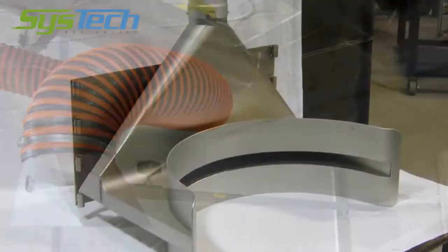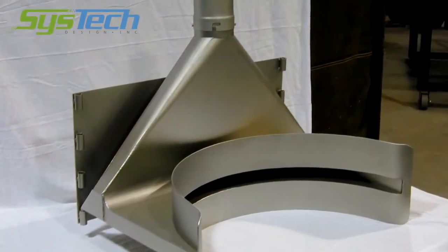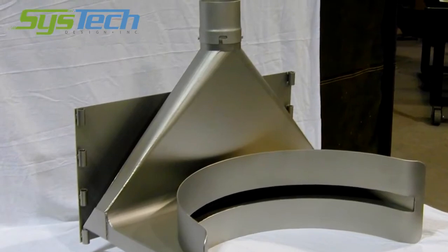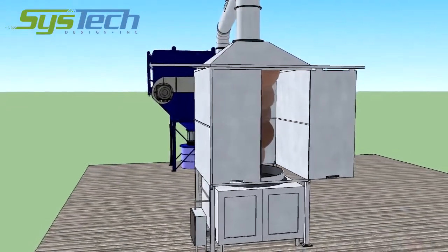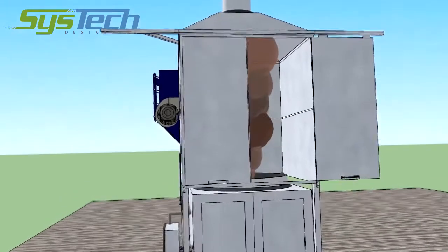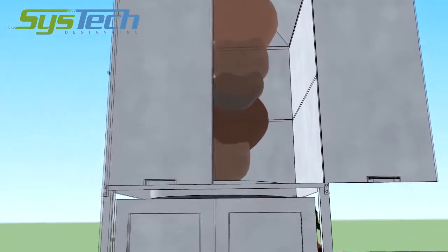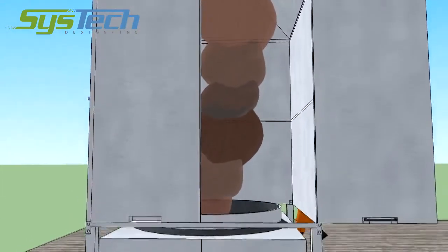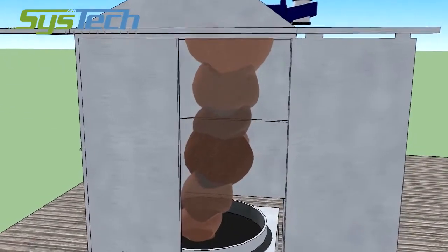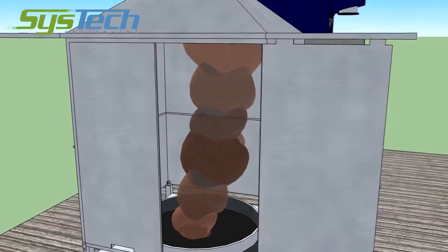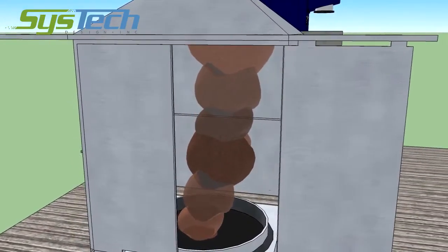A capture hood may be a simple scoop design, a multifaceted hood design for hazardous pollutants or potent compounds, or an entire room enclosure. Our video shows an enclosure mounted above a scrap metal melting pot with access doors on tracks, completely encapsulating the process. The doors on the hood are closed during the melt, reducing the in-draft velocity needed for containment while reducing horsepower and collector size.